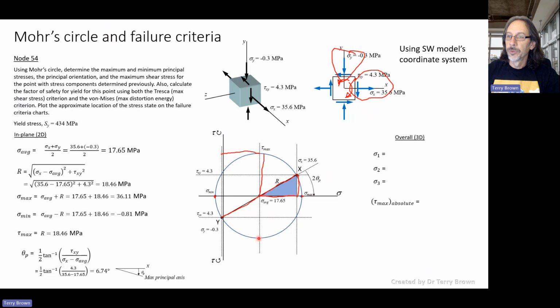We'll see that the stresses in the new X and Y orientations will be equal to the average normal stress. Now the 3D Mohr's circle, we look at this face out here, in this case the Z axis. And we can see that there's no shear stresses on here. So this is also a principal stress.